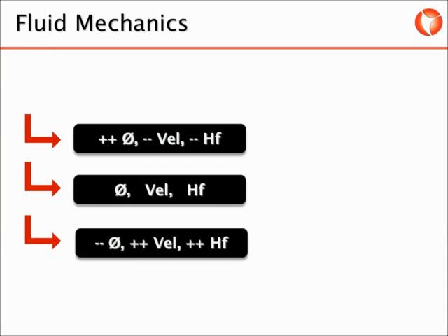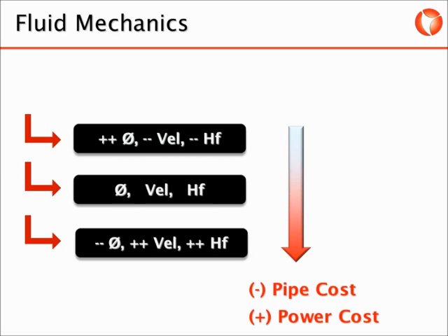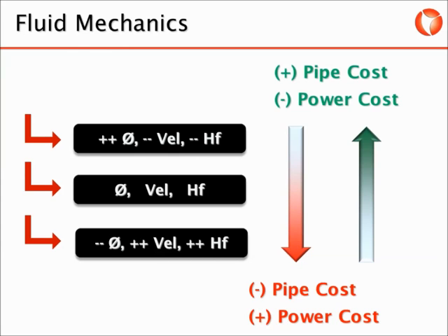If the capital investment of the installation needs to be reduced, the pipe diameter can be reduced, increasing the velocity of the system and thus the pressure loss. Summing up, reducing the diameter means less initial investment and more pressure loss, in other words, installed power. On the contrary, reducing the pressure loss will require slower velocities and in turn larger diameters.